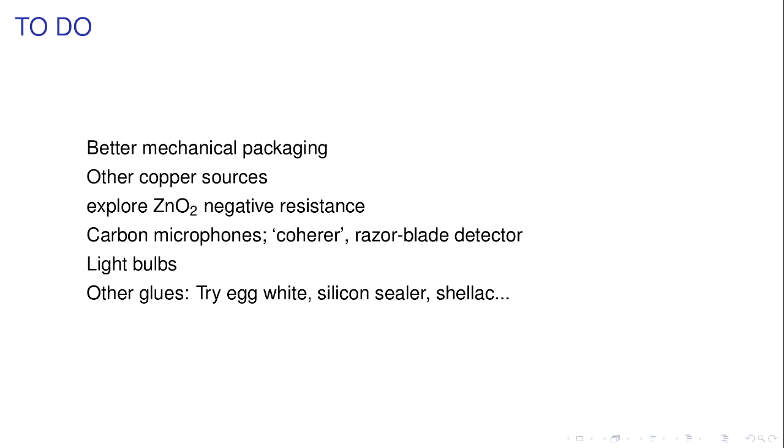And so you can make yourself a touch panel. I haven't done this, but my friend did, William Hallstrom again. You mix your silicone sealer with the graphite, spread it over a bit of card, nice and thin, embed wires on either side, and then, depending on where you touch it, you'll get different resistances between the wires. And so you can have a crude touchpad made out of stuff you can find at home.